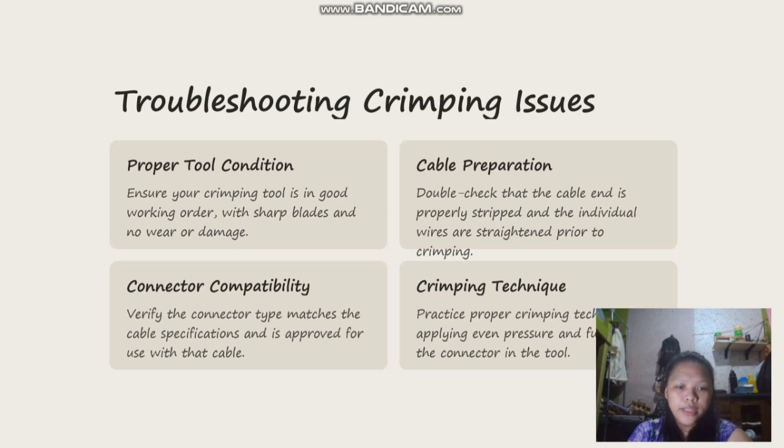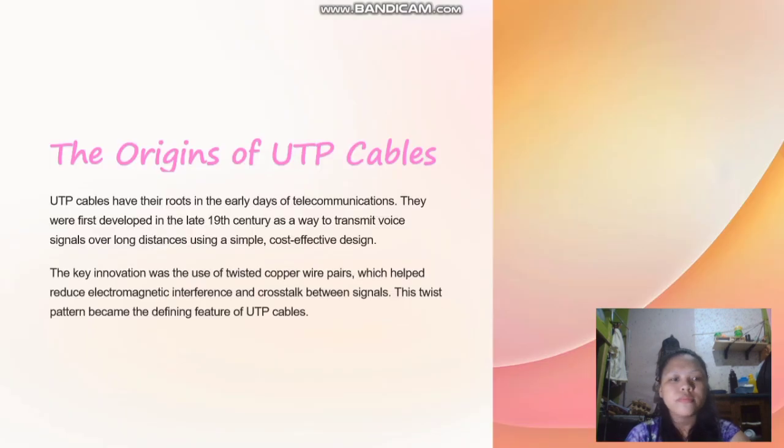Connector compatibility. Verify the connector type matches the cable's specifications and is approved for use with the cable. Crimping technique. Practice proper crimping technique, applying even pressure and fully seating the connector in the tool.